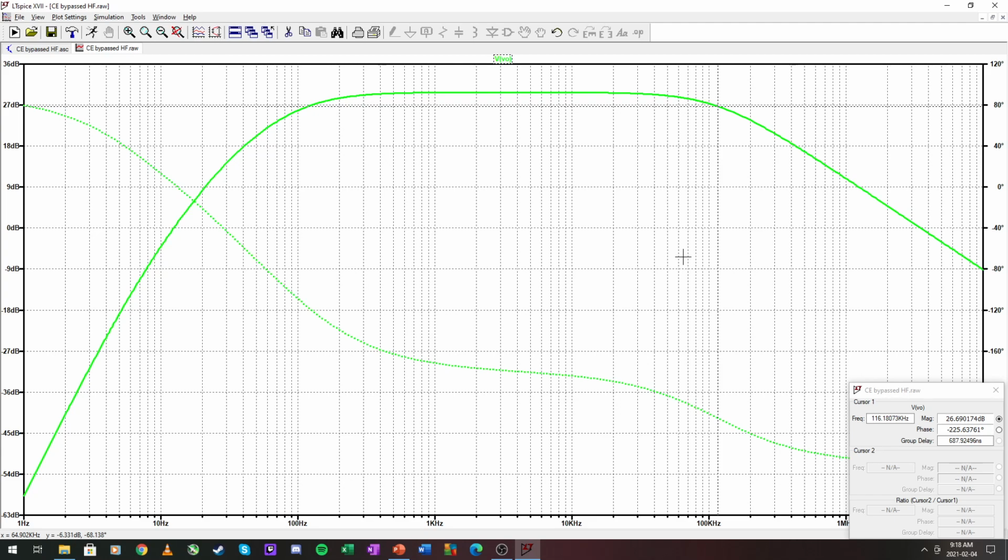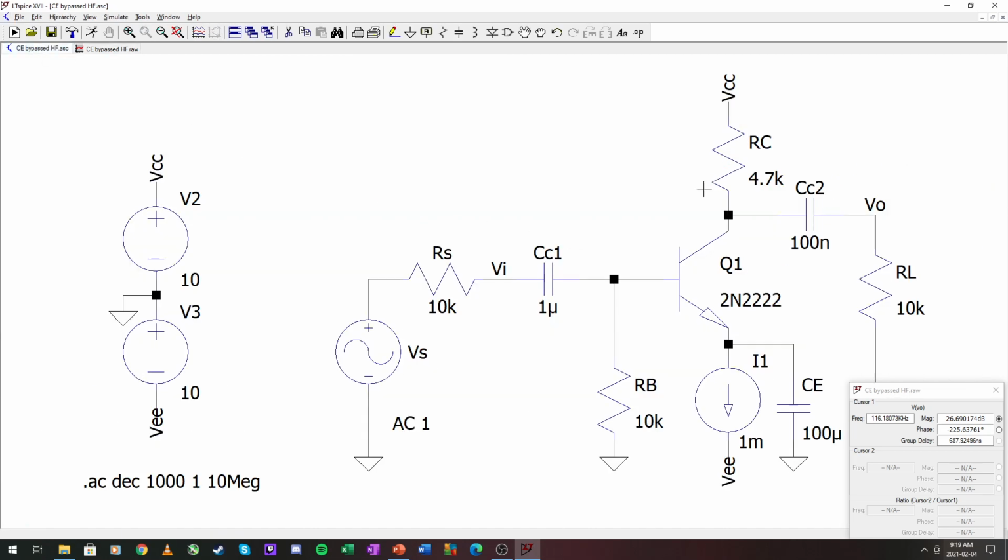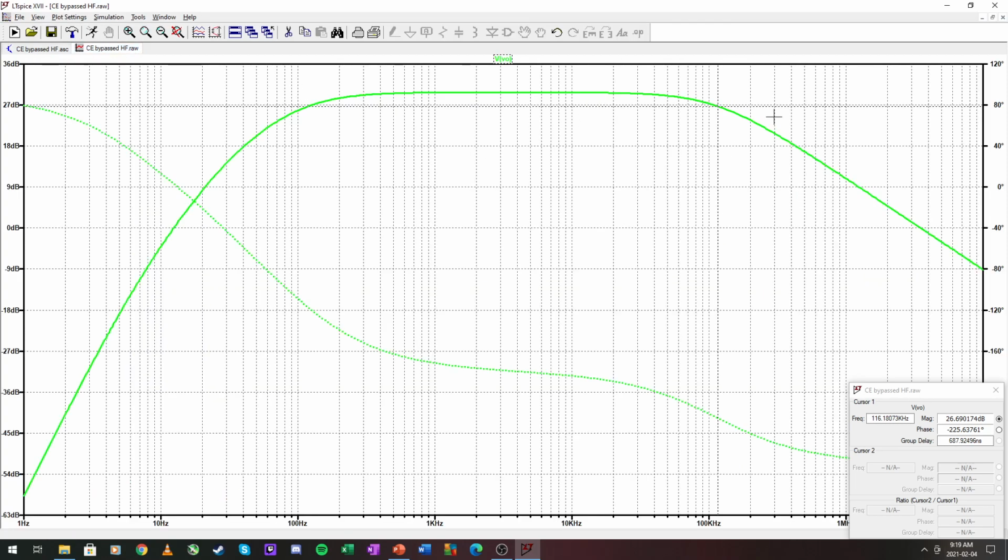And that seems like effort if you're doing a hand analysis. That is why we have simulators. At the end of the day, when you're designing, you want an estimate of what this frequency is, to help you design compensation capacitors. Right, so the high frequency is fairly accurate.